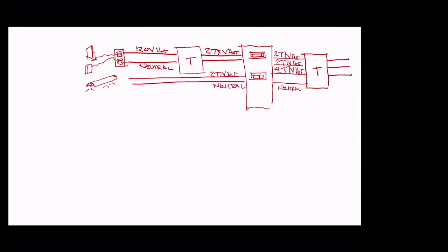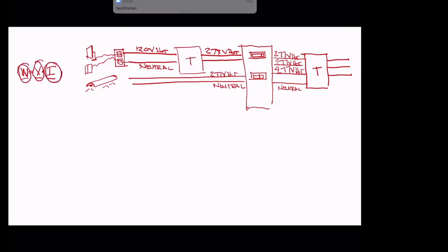And because watts equals volts times current, which means that the power is equal to the pressure times the wire size, because of that, if we increase the voltage to get the same amount of power for the lighting, we can decrease the wire size. And by decreasing the wire size, then we have saved ourselves a bunch of money. It doesn't seem like it would be a big savings, but in a big building, it actually really adds up.